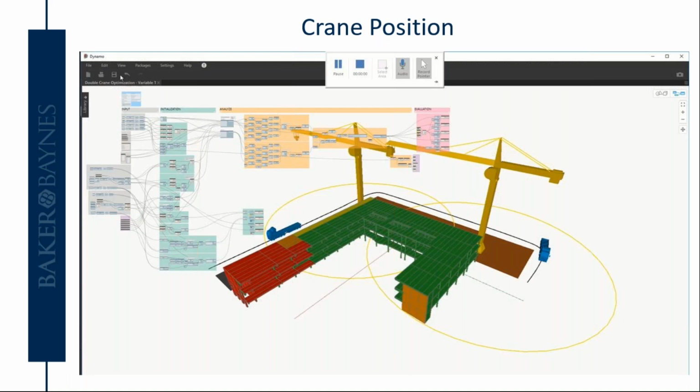This little clip is just going to give an overview of a Dynamo script that was created by an Autodesk technical consultant, and it was specifically designed for a precast building that requires trucks to enter a site on a given route, and then these trucks will have the precast concrete panels on them, and they will be lifted by the cranes that you see on the picture, and then placed into position in the building where they need to be. So a contractor would typically need to order these cranes and then also position them in the best location where they can both reach the back of the truck to pick up the concrete panels, and then also place it in the correct location of the building.